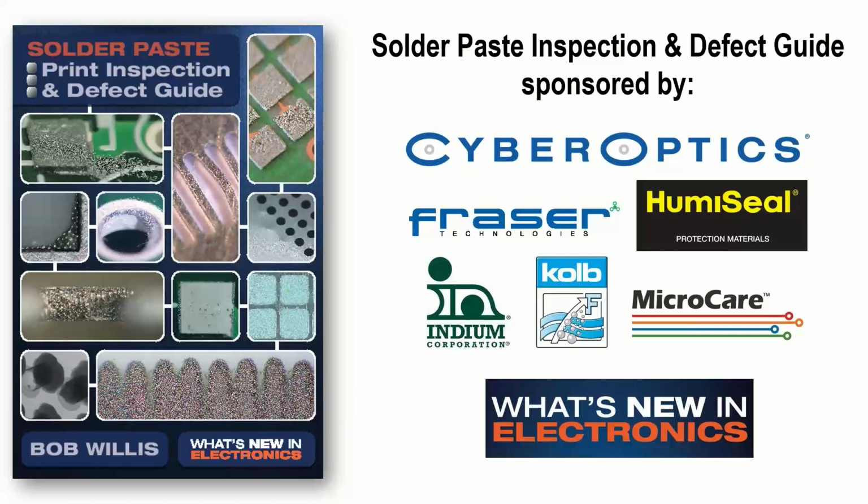You might be looking at individual tooling pins, etc. But if you use tooling pins, whatever type or style which are available from different stencil manufacturers, different printer manufacturers, the key thing is putting them in the same place all the time. Now, of course, some of the fancy printers put them in place for you.